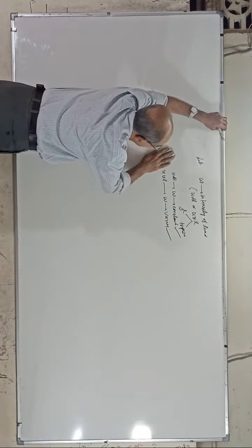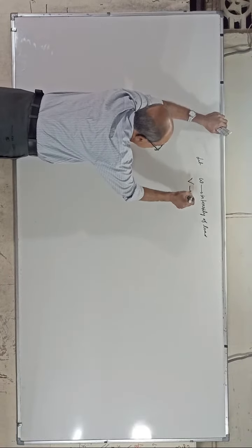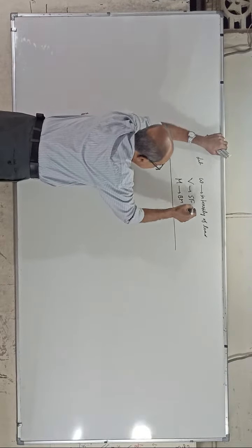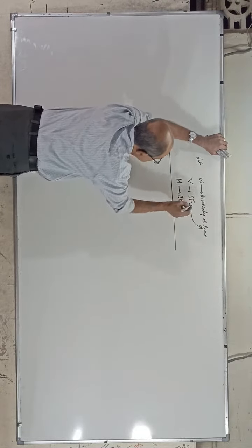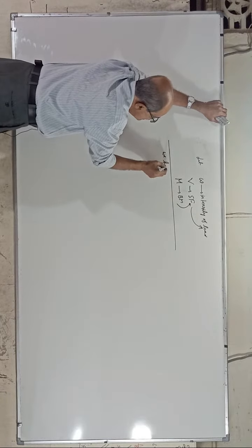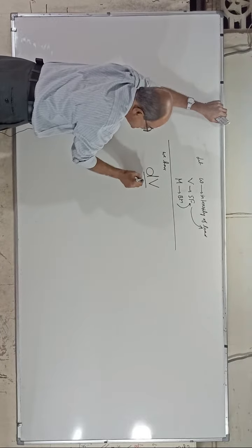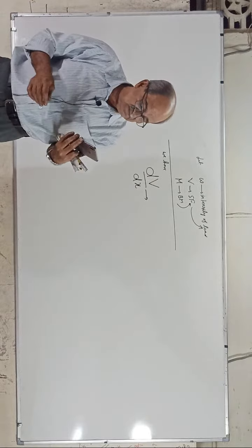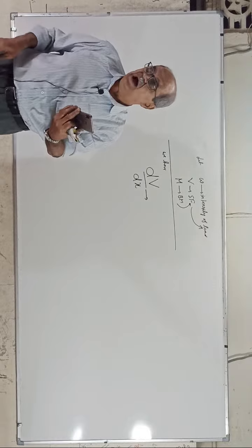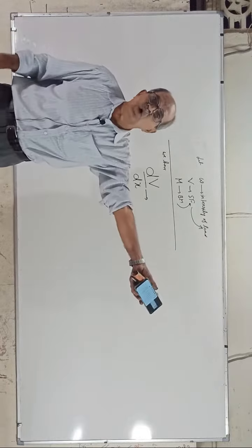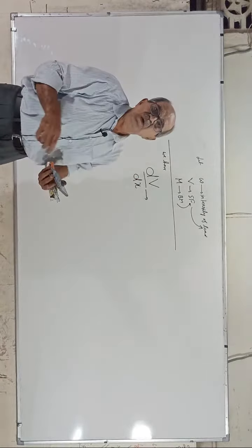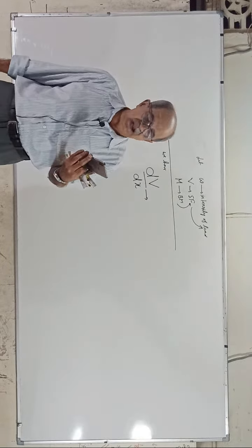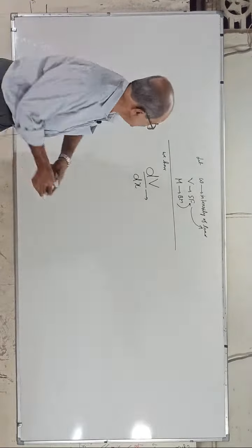Okay, now, before going further, intensity of load is w, then let V be the shear force anywhere and M the bending moment. Now, the most powerful thing: there is a relation between shear force, intensity of load and bending moment. First remember, we have dV by dx. Anybody can tell me what is dV by dx? Otherwise, I will tell you. In my SFD BMD course on YouTube, this is explained very thoroughly, maybe class number 33 or 34, the relation between bending moment, shear force and intensity of load. So dV by dx is the intensity of load.